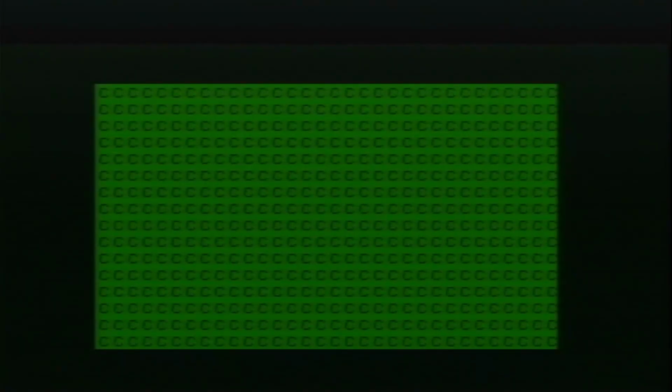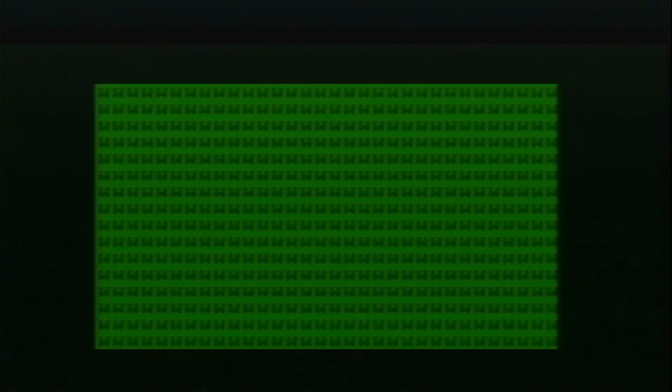An additional side effect is that in NTSC, you lose the colour from the display. Keeping the phase correct within a single frame should be simple enough, but DA0 is not clocked all of the time. It pauses for the border area and needs to be cleared on vertical sync. The problem is that it has to be cleared exactly the right tick within the vertical sync, and this has caused me no end of grief.